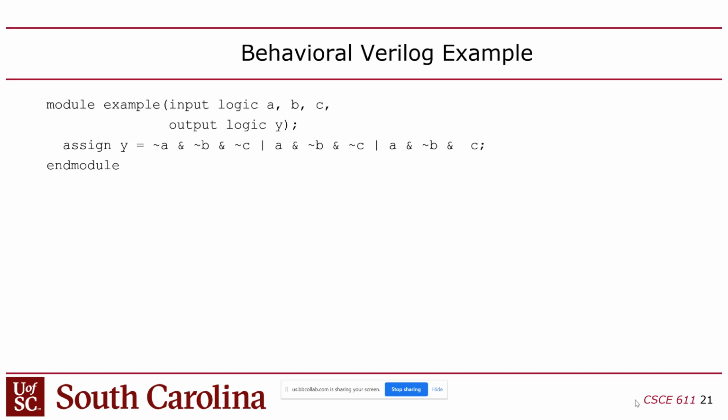It's weird too, because in VHDL, if you do that, it'll say iteration limit reached, at least in ModelSim. It figures out that something's wrong, that it's been spinning for too long and the simulation doesn't converge. But for whatever reason, in Verilog, it just hangs. It might be a limitation of ModelSim.